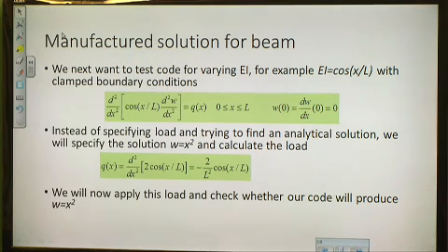So that basically tells us if we will apply this wind loading, it's of course the wrong model for wind loading. Could anybody tell me why this is an unrealistic wind loading? I think one assumption is you are solving it in one dimension. I'm sorry? You are solving it in one-dimensional case. Yeah, this is a one-dimensional model of the building, so I have to apply one-dimensional wind loading, but you see, this is wind loading that would be maximum on the ground and then reduced to about half at the top, while we expect the wind to go in the other direction.